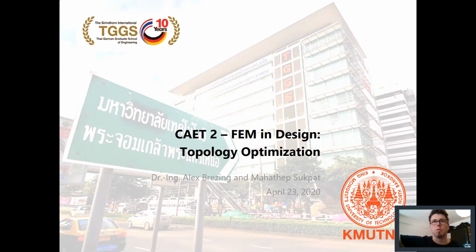That structural problem would be how much space you have for material, basically, which spaces you cannot change for optimization, what loads are acting, and then after all of that, the optimization goals that you define. That would be, for example, the minimization of weight. So basically, it's about saving materials and weight, but there are different targets you might have.